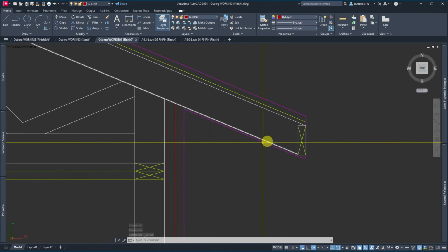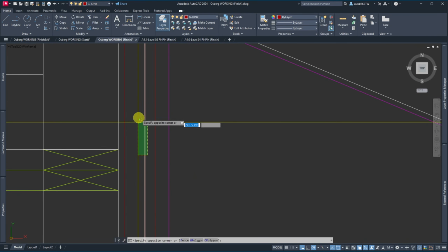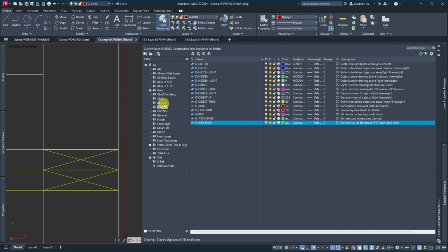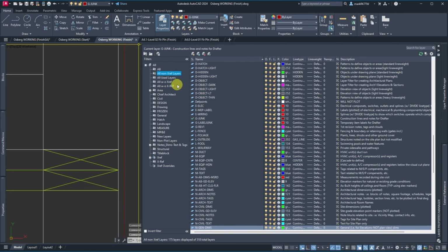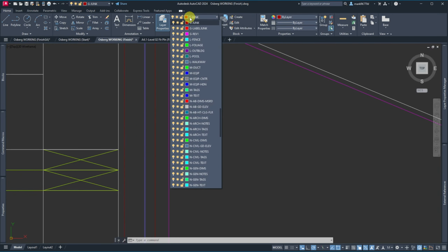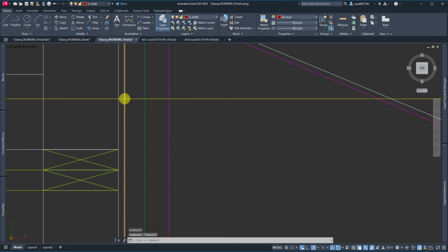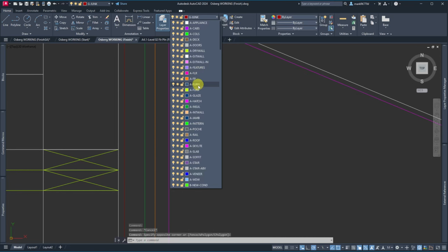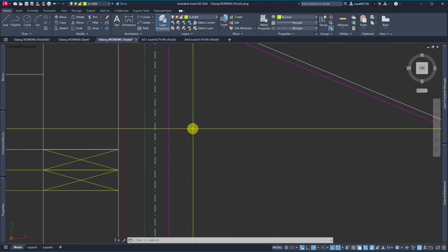So over here, we're going to look at our wall layers. This is an insulation layer. So I'll just come in here. I think it's in the A's. Oh, my layer set's not correct. I'm set to drawing, which simplifies my layer set quite a bit. So I'm going to come up here. Now, I have that selected still. I'm going to hit A, and I'm going to come down to my A insul. And then this one is a furring, so it's an A fur. And that holds my insulation in place, just 1x4s that hold the insulation in place.